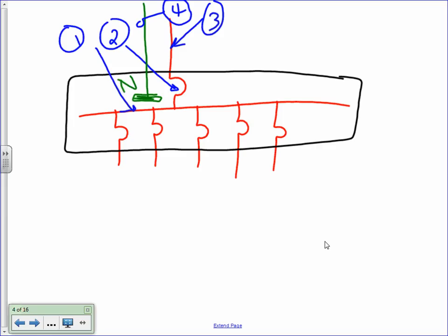And I'm going to go back when you sketch that one. That's basically what we're trying to achieve. We're trying to size the panel. Exactly, Jeff, what we did, we sized the panel at 3,000. The overcurrent device was 3,000. Now we're going to size the conductor to feed a 3,000 amp panel and the neutral to feed a 3,000 amp panel.